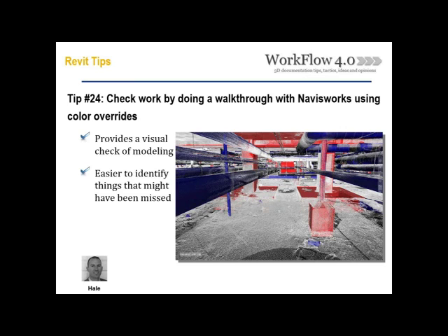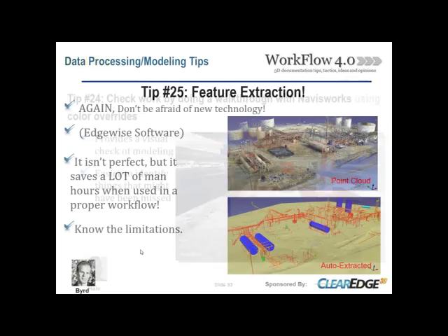So you have basically both data sets, both the virtual model and the scan data, and you're able to walk through that. It's probably the best way that I know of to find missing data or find where you might have made a mistake in your modeling workflow. You just get views from all positions, and it's the same thing I talk about for an overall virtual modeling environment, is walk the model, find out where you might have missed something. It's a great tool.